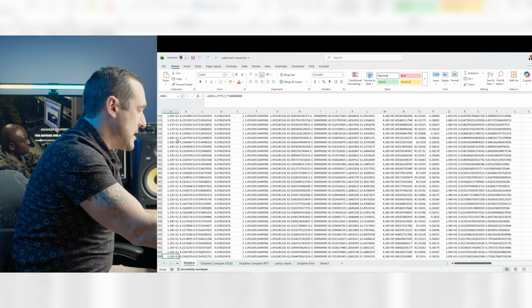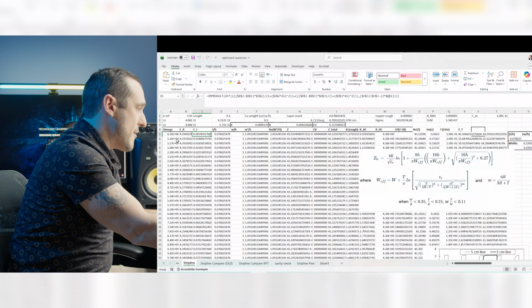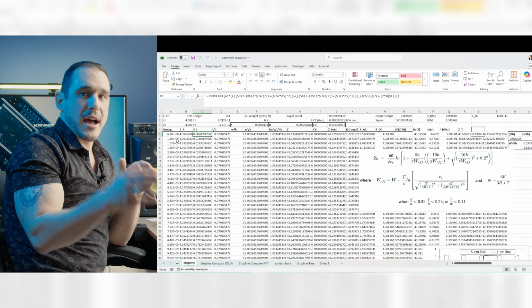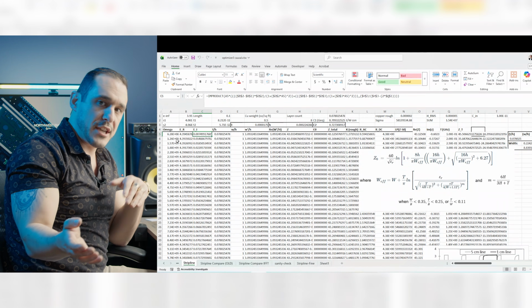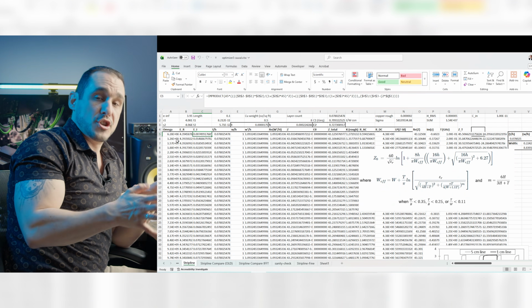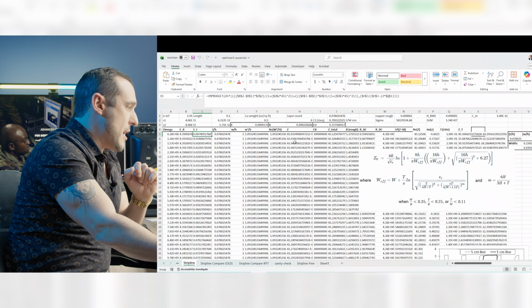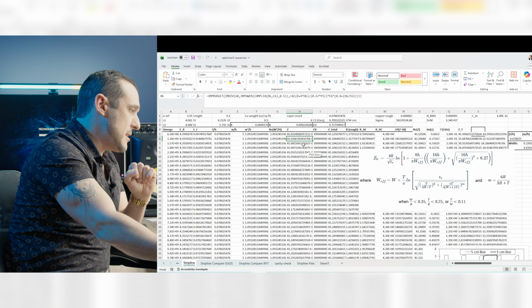So here you can see that we have our frequency range that we're considering. You can see here that we have a real and an imaginary dielectric constant. You can figure those out just by looking in data sheets. You can do interpolation. You can use, for example, a wideband Debye model, or you can just use a constant value across your entire frequency range. And then you can see here we have our geometric parameters, which ultimately give us our lossless impedance.